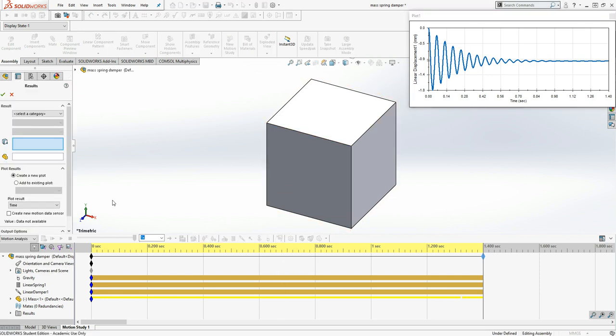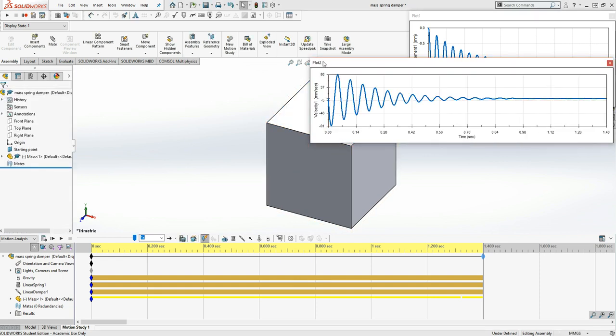Let's just take a look at our velocity, because you remember on the Simscape model that we built, we did pull out velocity and also acceleration. So I'll do velocity, and I'll leave you to do acceleration. So I've picked velocity, and I'm going to go in the Y component, and I'm going to choose the top plane again. Again, if you're starting to measure the same place for different things, make sure you stay with the same position. Sometimes it can affect your outputs. Not all the times, but some. It's just so it's healthy to always stay with the same selection. Click OK, and there we go.